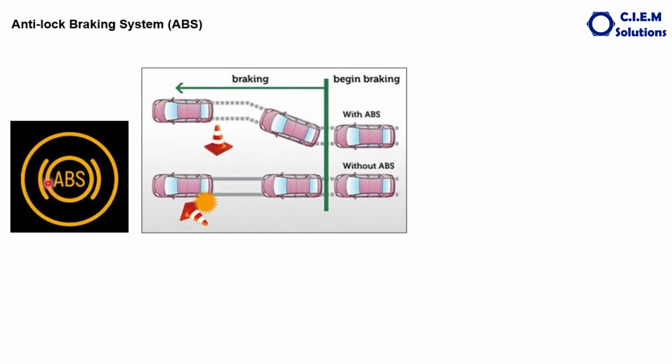This itself indicates releasing and holding. You observe this figure. This figure indicates the vehicle without ABS. Beyond a certain speed, if you want to avoid collision, this vehicle cannot do so, because the differential speed is not maintained between the inner and outer vehicle, whereas the machine fitted with the ABS can negotiate this curve and avoid the collision with this object. This is how ABS functions.